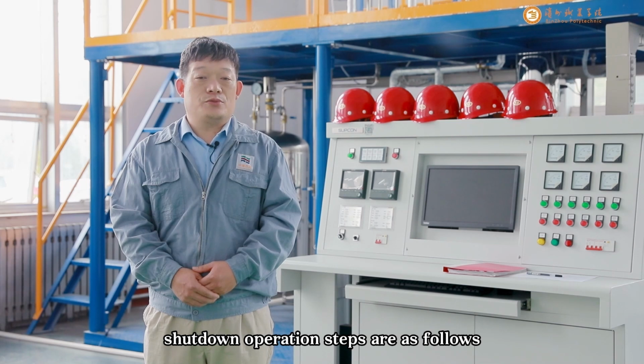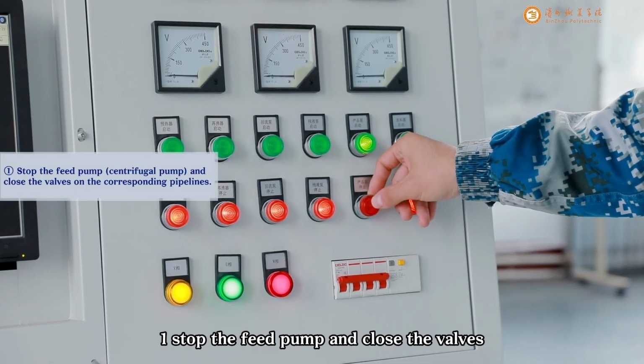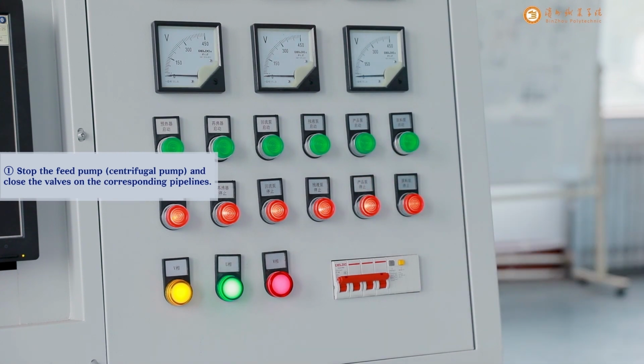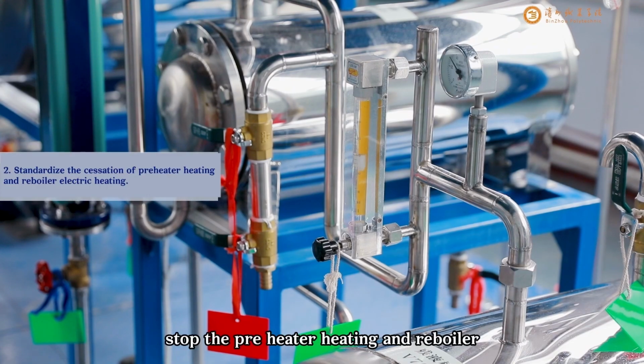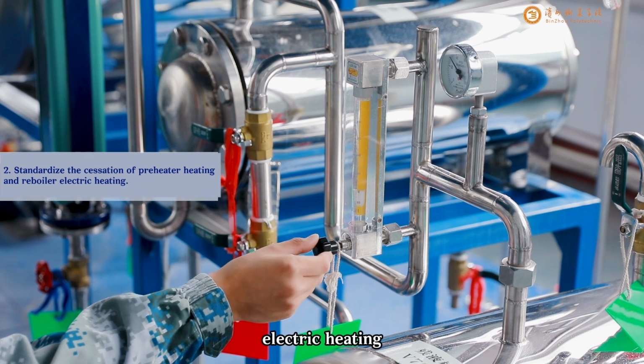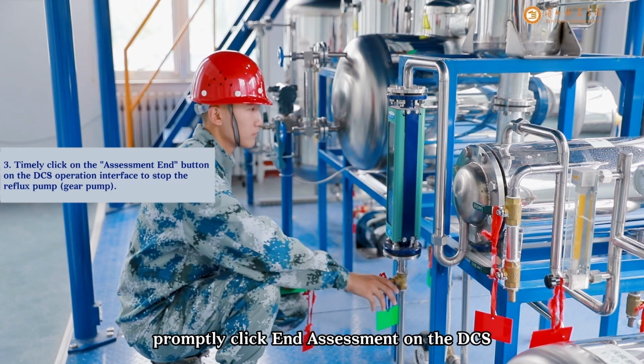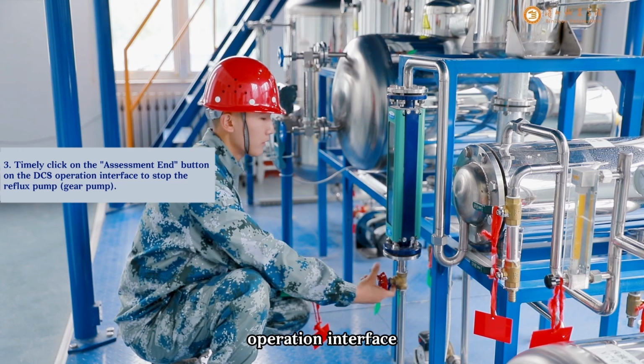Shutdown operation steps are as follows. 1. Stop the feed pump and close the valves on the corresponding pipeline. 2. Standardly stop the preheater heating and reboiler electric heating. 3. Promptly click End Assessment on the DCS operation interface.